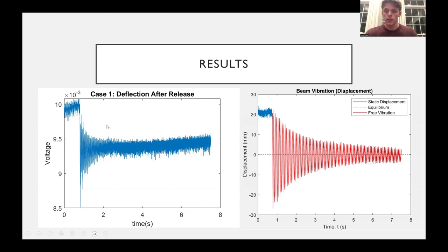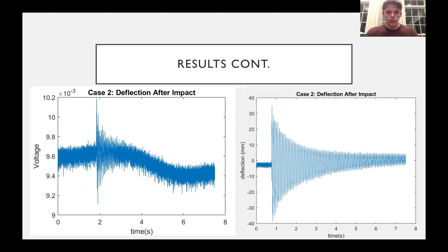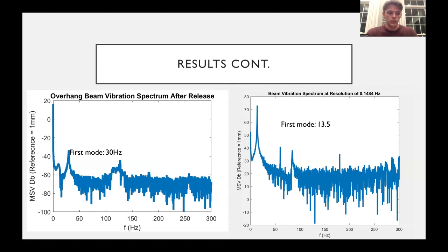I do believe that there is a lower sensitivity on this beam because more of the bending moment is distributed across the beam. And that's why we're getting lower voltages at that initial displacement. If I pictured that data from the beginning, you would be able to see that. But similar results here. I'll move on from this to the spectrum analysis.